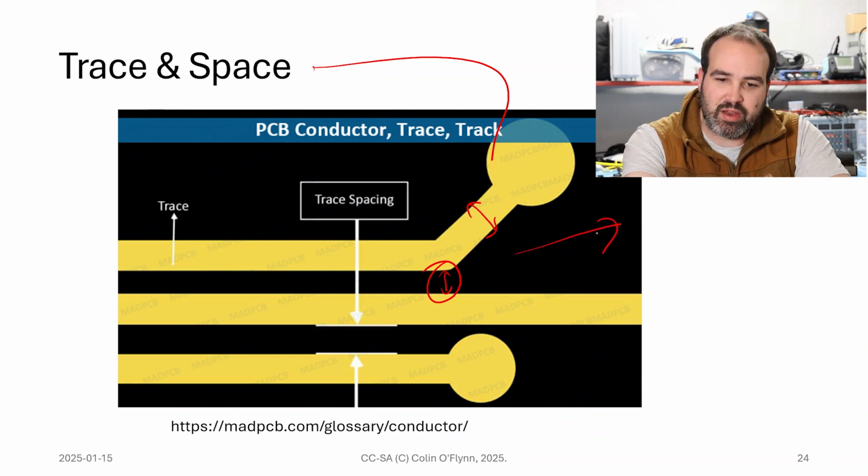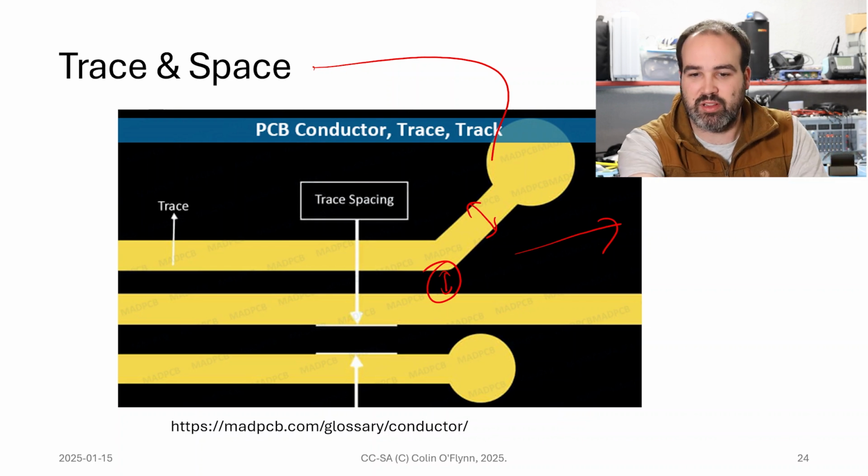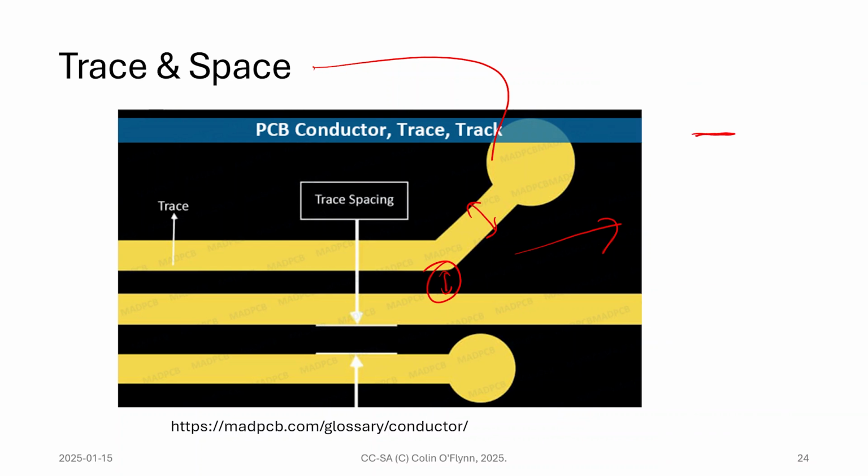Why this comes up is, we still etch, like all of this fancy work is still using that etching, like those tanks I showed earlier. And so when you etch, you have copper, and what you tend to get is some under etch. So if I have my copper on my board, the traces, this is the resist. This is the part where I've said, don't allow the etching to get to my copper, but it's going to go around the side a tiny bit.